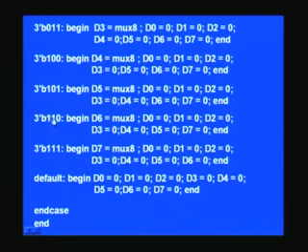There is no guarantee these inputs are exactly a valid number here, and it may be an X, that is a don't care, or even a Z, a tri-state condition, and in other cases you may not have used all these conditions. In such a case, this default is a mandatory thing, otherwise it will infer a latch, and you will run into problems later on.